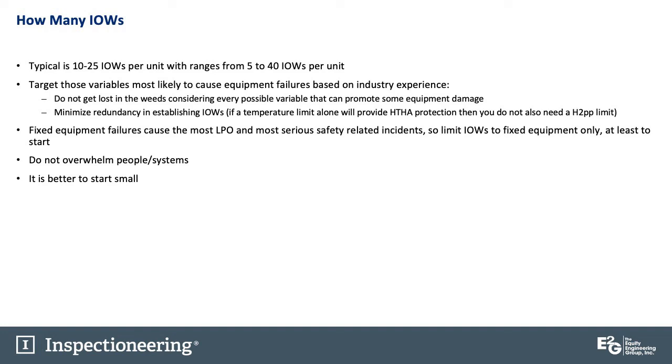How many IOWs? You'll get some debate in industry on this. I'm a believer in trying to keep it as simple as possible and quite targeted. So from my experience, typical is 10 to 25 IOWs per unit, with some ranges from 5 to 40 IOWs per unit.